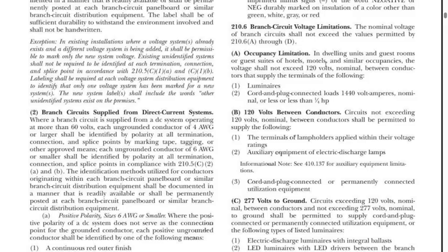Now what A is saying is, in homes, in dwelling units, in a house, or a guest room, or a guest suite, hotel, motels, and Holiday Inns, the voltage shall not exceed 120 volts on these circuits. These circuits are lights and generally what you would plug into your standard outlets, which is really small motors.